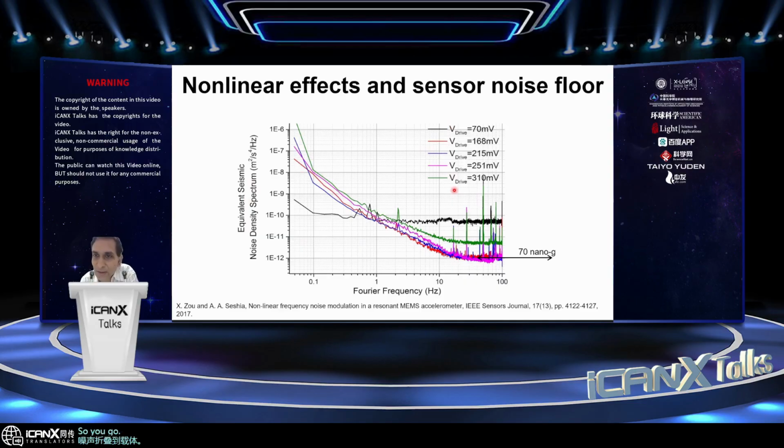So you've got potentially a combination of effects where the nonlinear response can mediate that noise folding to the carrier, and thereby degrade the low frequency performance of these sensors. So this was studied through a combination of experiment and modeling, and also tying in some previous work from our group in the area of MEMS oscillators. So you can start to then look at optimum drive levels and that sort of thing, depending on the application of interest.